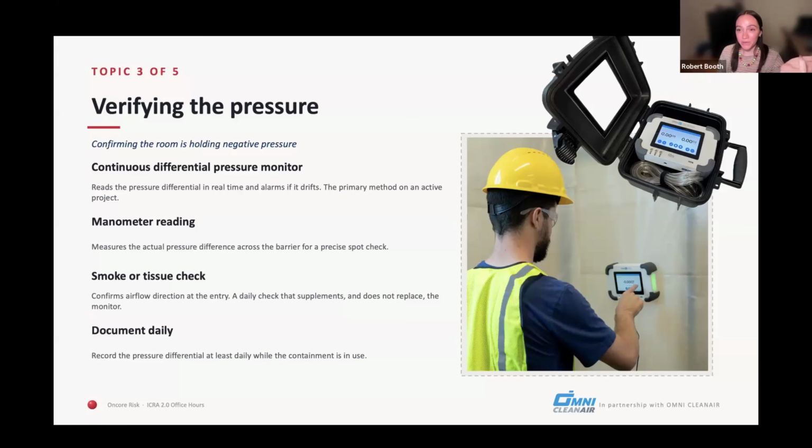We work in hospitals. We help develop particulate monitoring programs for hospitals, and they'll say, oh, we'll just give a particulate monitor to one of our guys. He'll go check it. This particle meter is 10 years old. It's never been calibrated. It's not defensible.